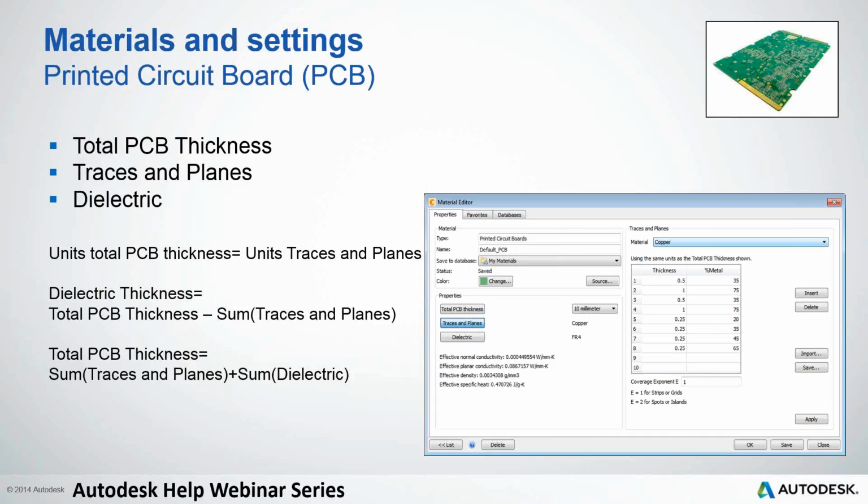So next is applying the material setting for the PCB. You have a couple different options here. In CFD, you could actually grab one of the many default PCB boards under solids, which have a standard 12-layer, and you can base orientation to get your conductivity right. If you want to make your own PCB material, it's absolutely fine, and we have a whole section of materials for that.